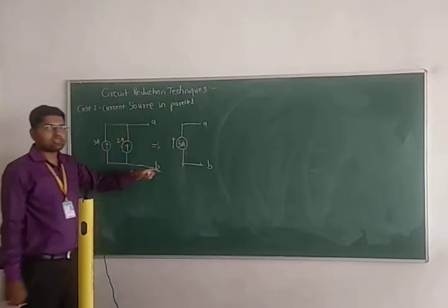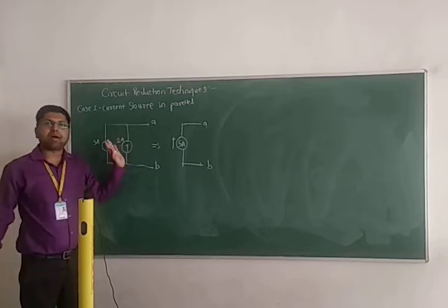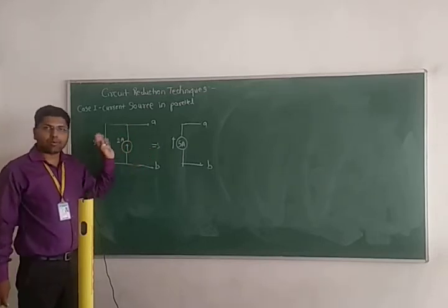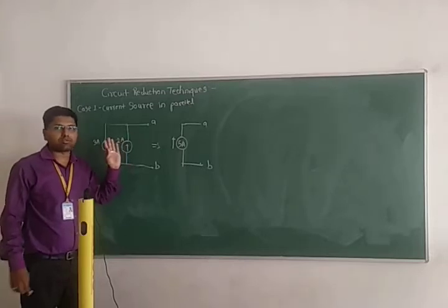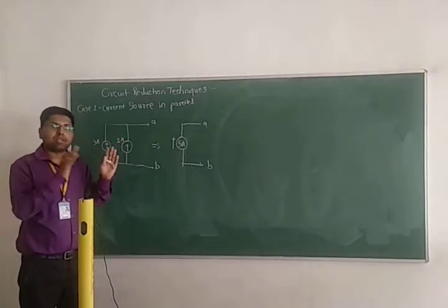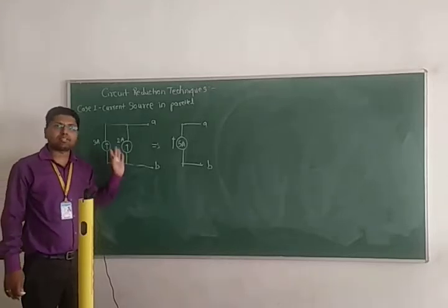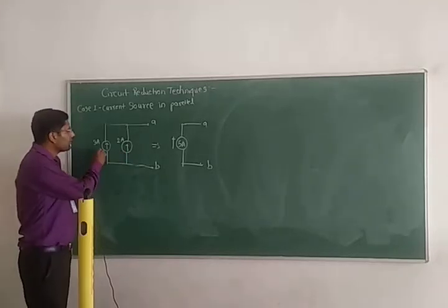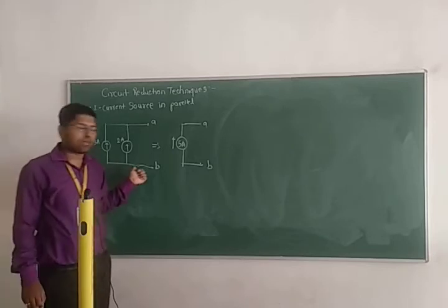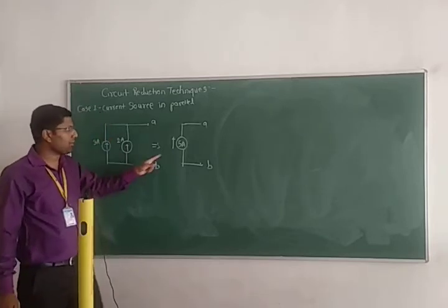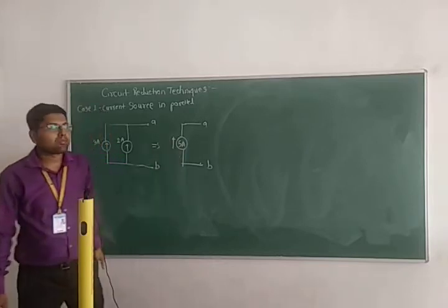Okay, so that is the simplification of the parallel circuit when there is a current source. If there is a voltage source, you can't add that, because voltage is the same in parallel. In the current source, in series they are the same. So this is the circuit of the 3 ampere and 2 ampere; this is a 5 ampere circuit.